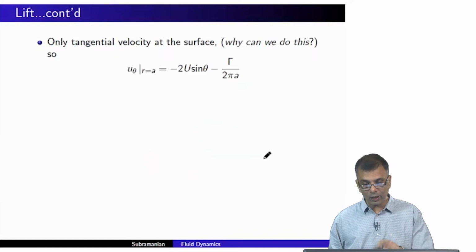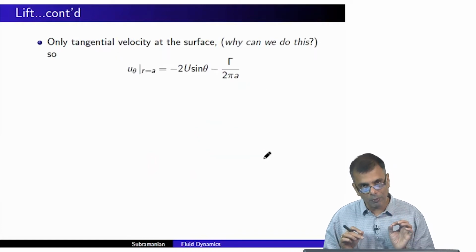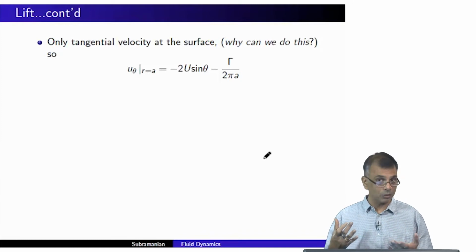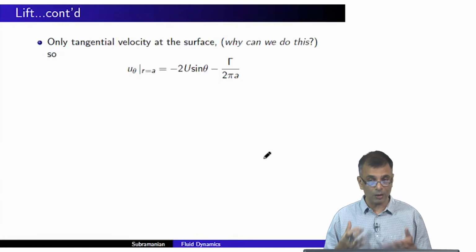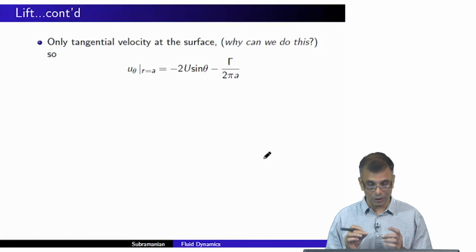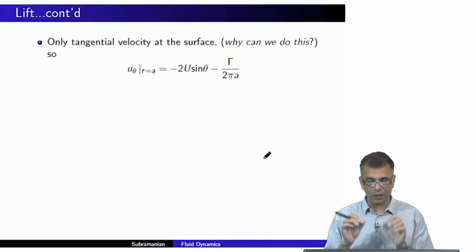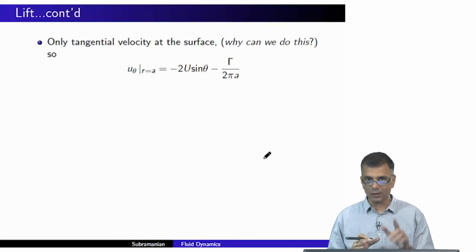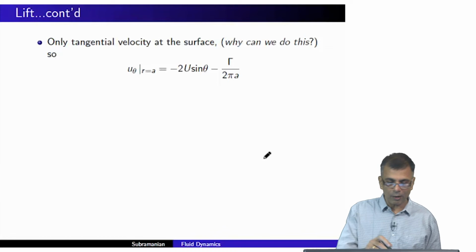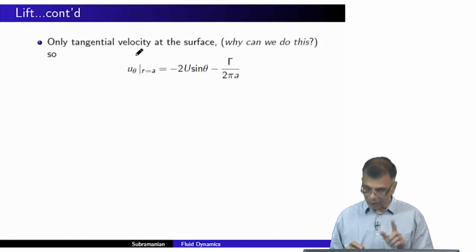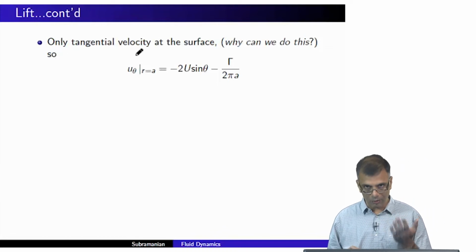And since we are retaining the potential flow solution while actually considering a situation where the viscosity is finite, definitely so near the boundary, nonetheless, as far as the mathematics is concerned, it's still that of potential flow. That's why we can have tangential velocity at the surface, unlike in a real world solution with viscous flow, where even tangential velocity is not allowed.